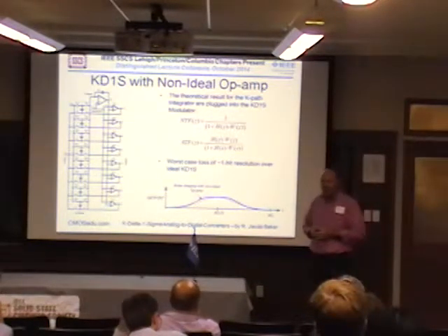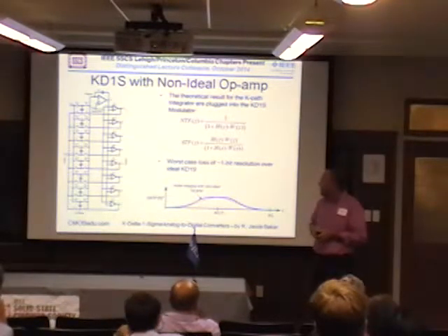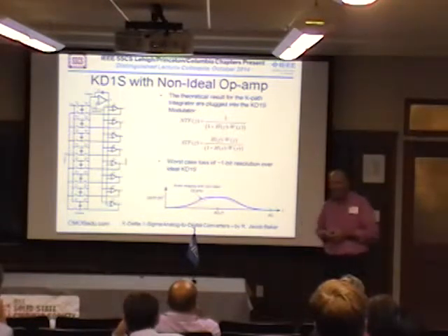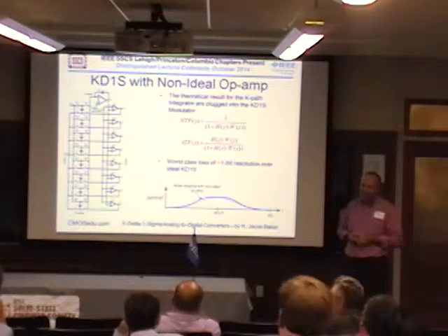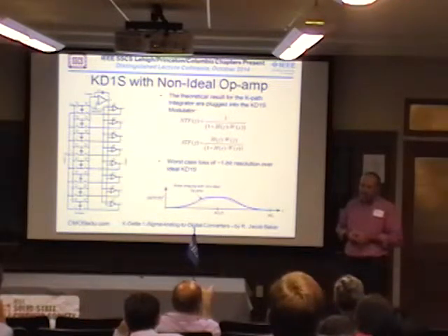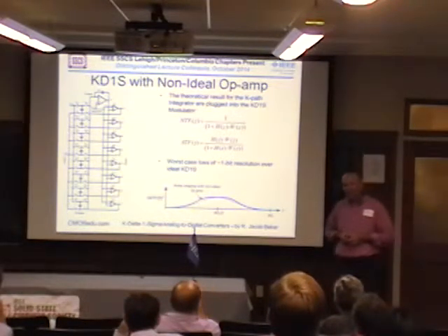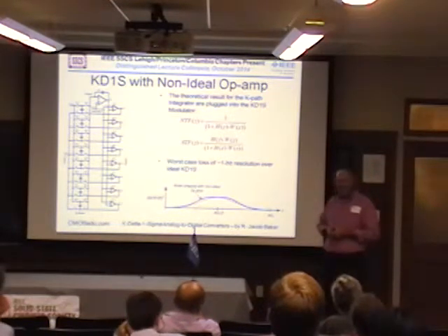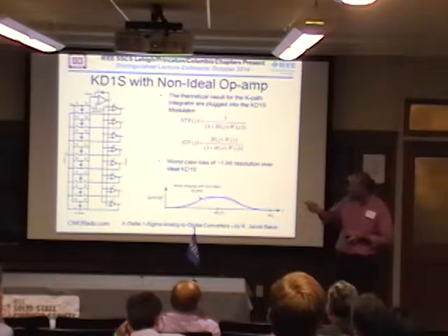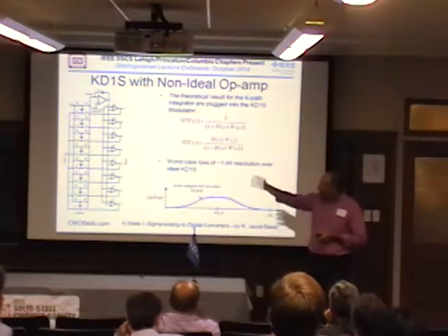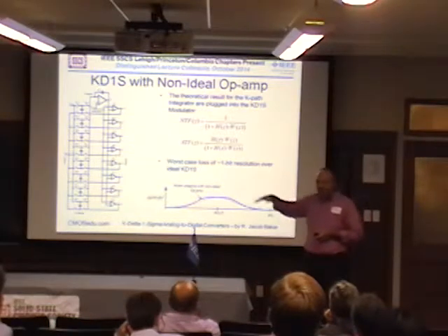Did you generate all of your clocks externally? No, that was on chip. We had a DLL on there as well. I didn't mention that. Have you pushed some of the need for precision onto the clock? That's a good question too. I kind of rushed over it because clock jitter is a huge problem. Well, and matching between the phases, like the capacitor mismatch.